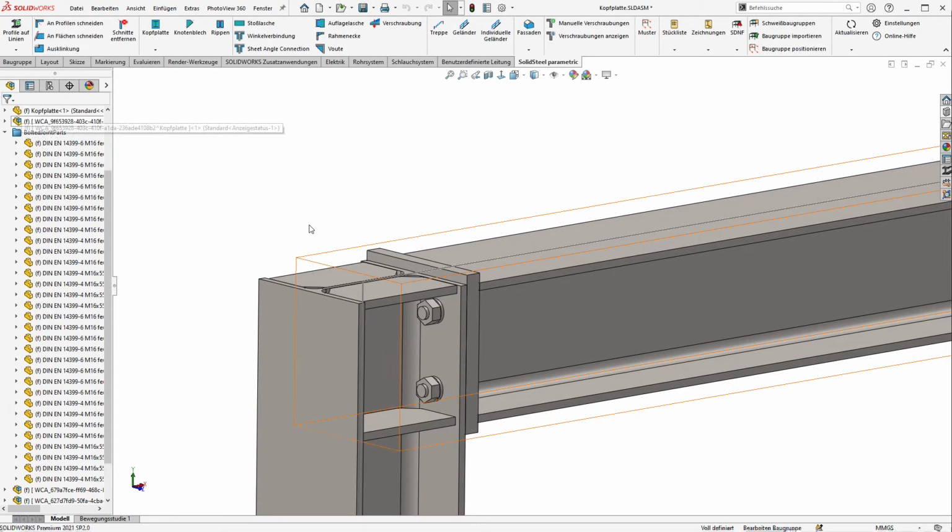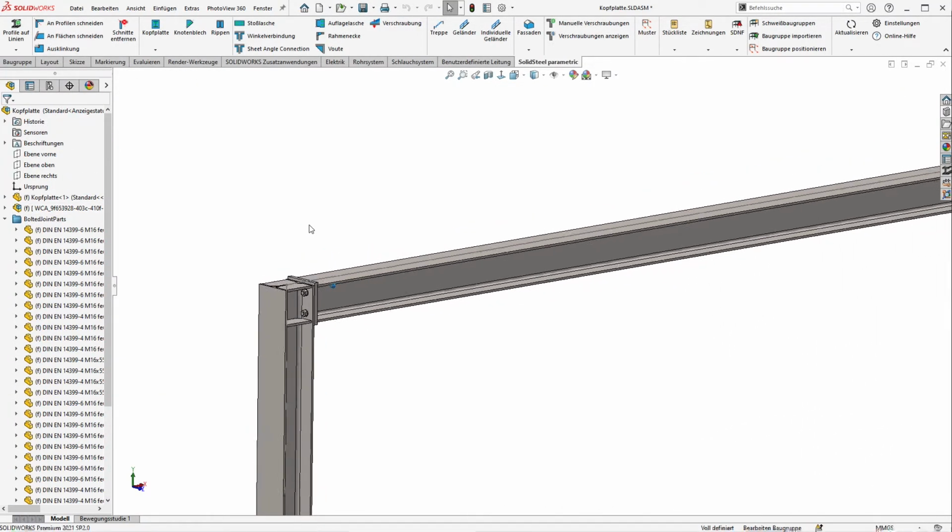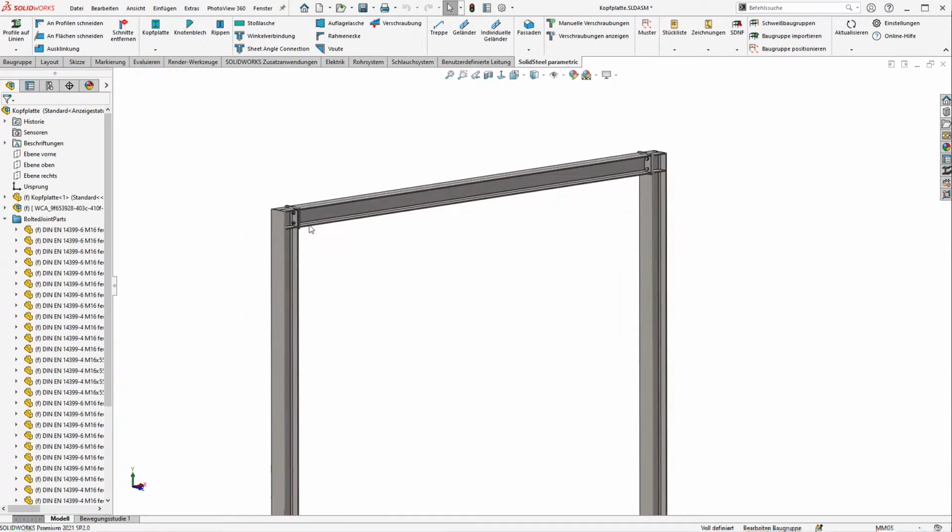Alright, that looks like a frame to me. Everything is complete with end plates bolted in place, the ribs sitting where they should, the profiles were automatically and correctly shortened, and welded assemblies were also automatically generated. With the profiles used, this is a very slender construction.